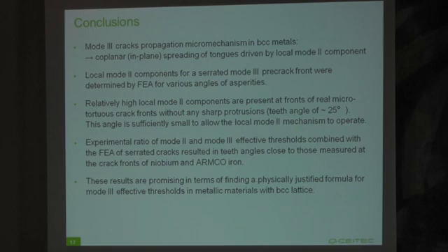We found that a relatively high local mode 2 component is present on asperities inclined by 25 to 30 degrees, and the results were in agreement with the experimentally measured ratio of mode 2 and mode 3 effective thresholds. This is what we want to do next, to formulate a predictive relationship for effective mode 3 threshold in the BCC metals.